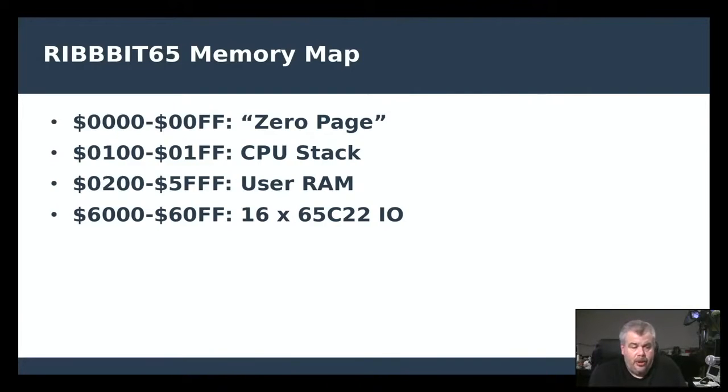Ben put I/O at 6000 hex, and basically that whole 8K block is out the window as far as RAM is concerned. Now, of course, that seriously simplifies the address decoding logic, but it does make things a little tough in terms of trying to make maximum use of the available RAM space.